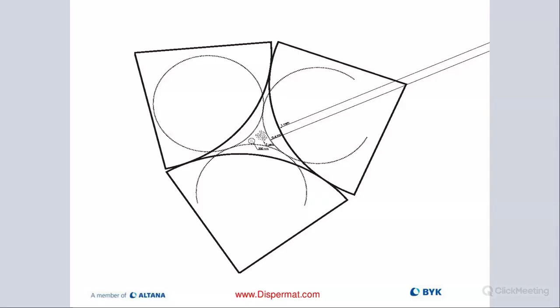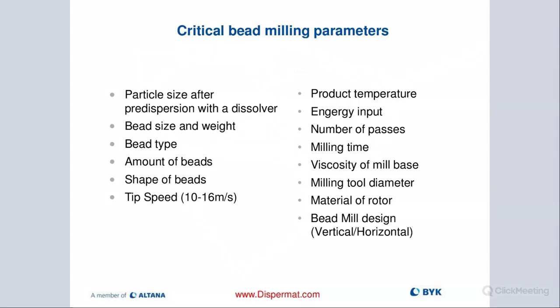And that's exactly what's happening inside of the bead mill. It's the same in a horizontal bead mill versus a pot mill or even a basket mill. The principle is always the same. It's really the shearing of these clusters that helps us to break them open and reduce them to smaller sizes.